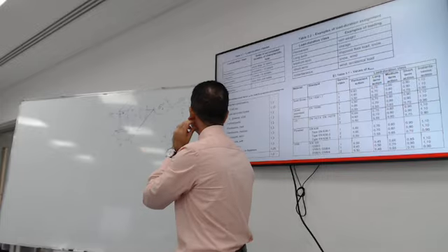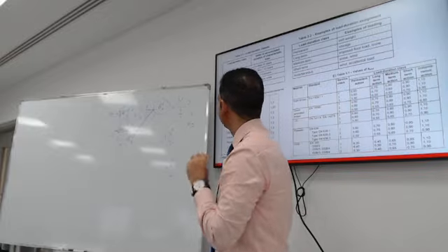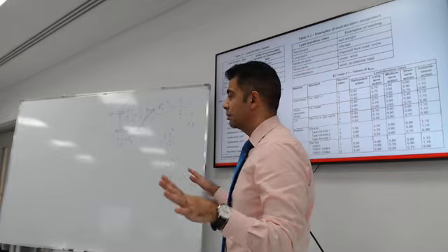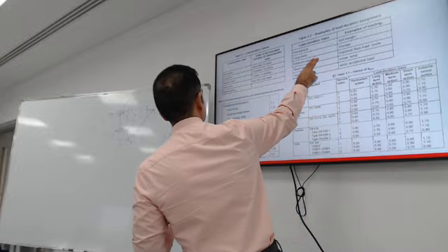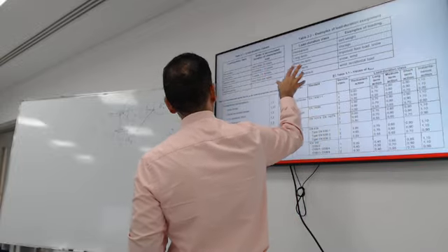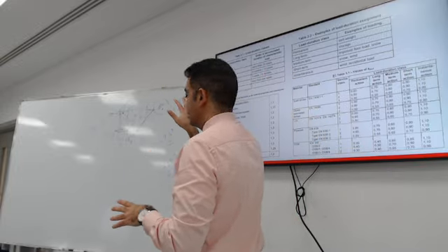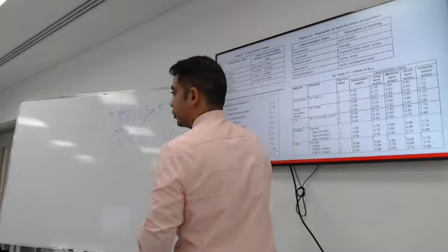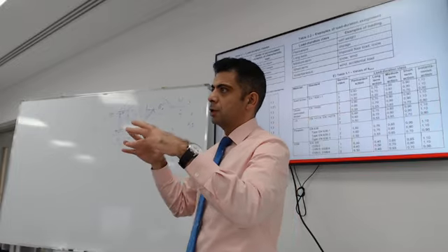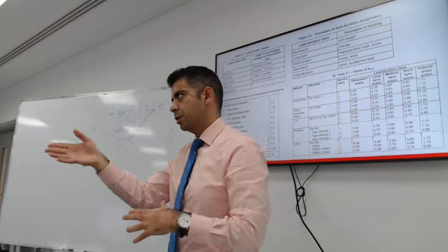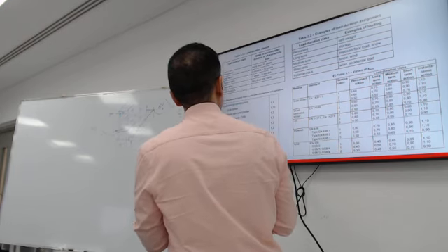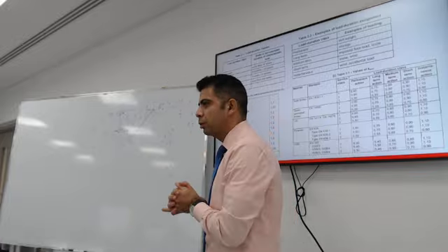There are 5 main classes. Permanent, it's always there. Self-weight, as an example. Table 2.2 gives you examples of these classes. The second class is long-term, if you have storage, furniture for example. Third one is medium-term. That will be like live load, snow.